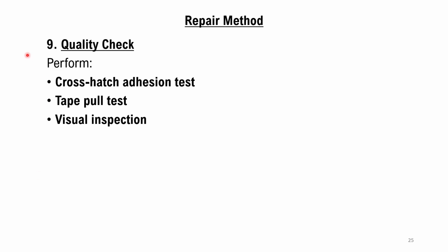Finally, check the quality of the repaired part. Perform a cross-hatch adhesion test or a tape pull-off test, and of course, the visual inspection.